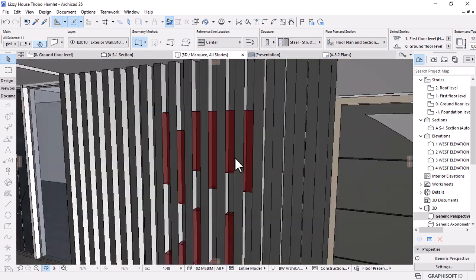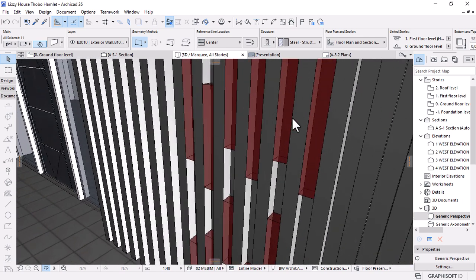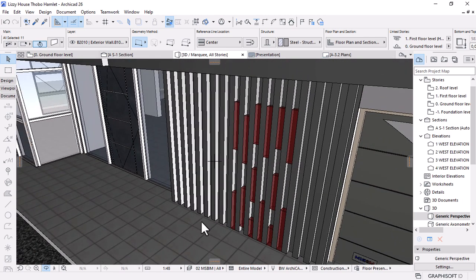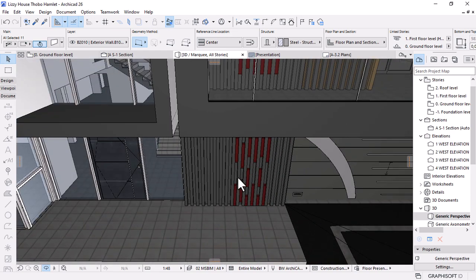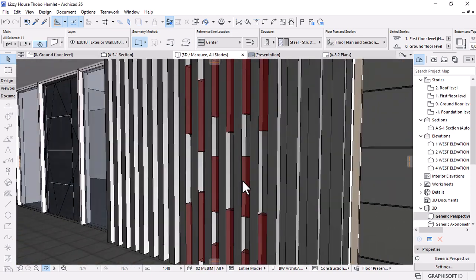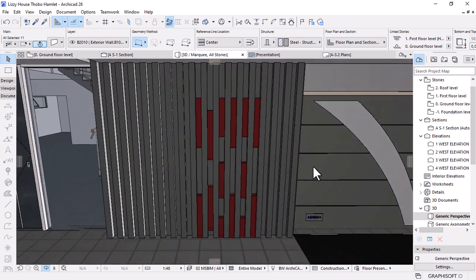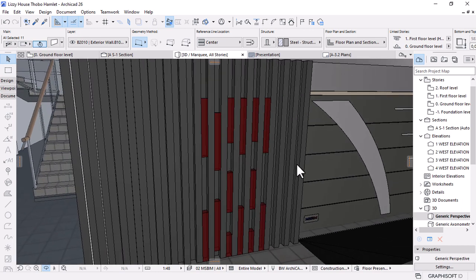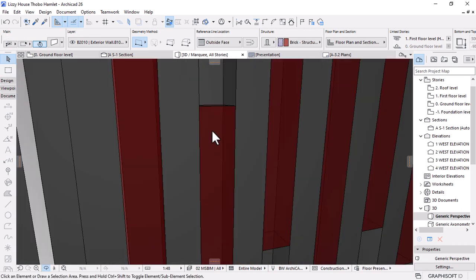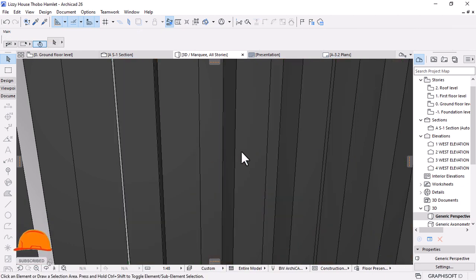By the way, I've used some perforations here to provide ventilation and lighting to the toilet, because when it's like this you can shade it to block it off from the natural light and ventilation. So we've created some perforations, as you can see here, to allow air to go in the duct. So yeah, let's hide this so that you can see this is supposed to be hidden.